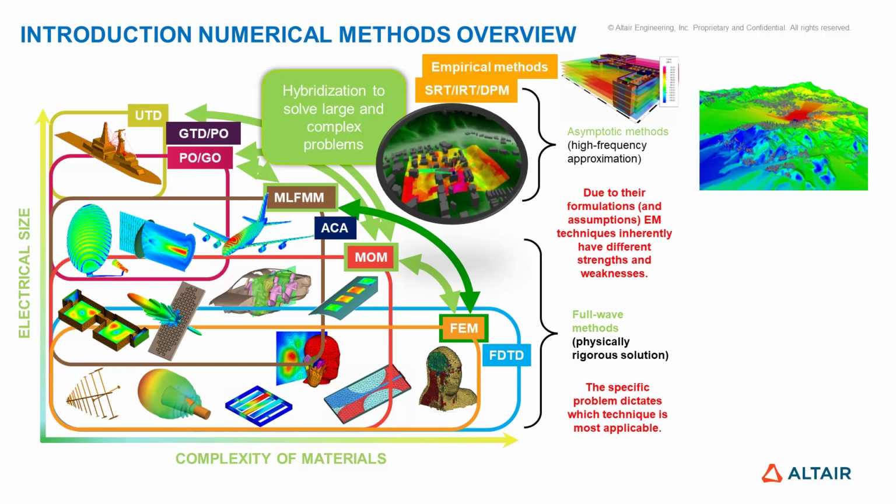If we start with antenna and circuit level design, one will need rigorous and accurate methods such as MOM or FEM. While if we are targeting a wide frequency band application, we switch to the temporal FDTD method. These methods are very well suited for small structures below 10 wavelengths and complex materials such as the human body or even circuit layers.